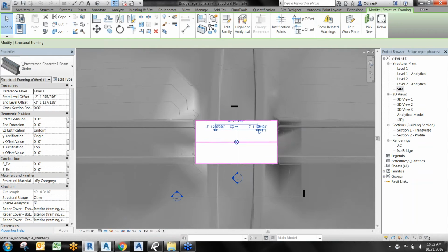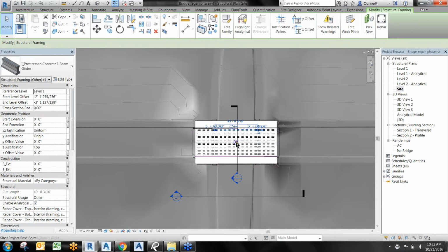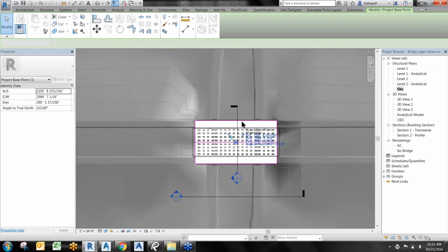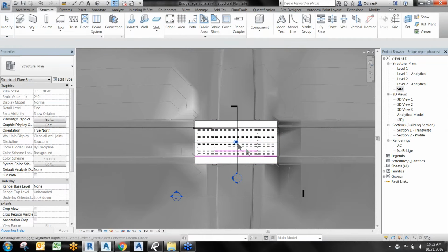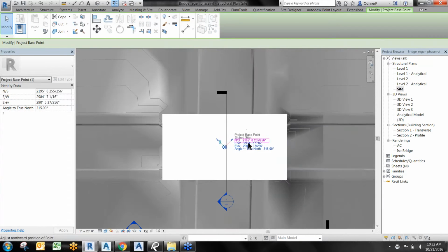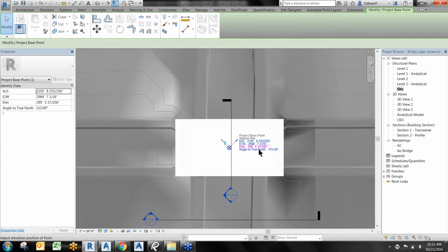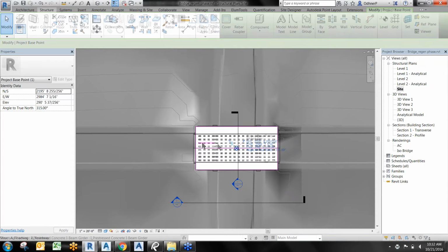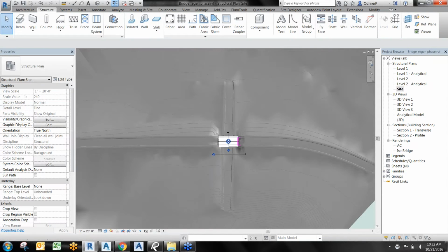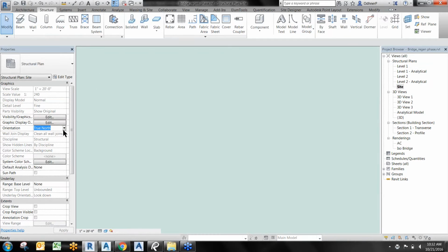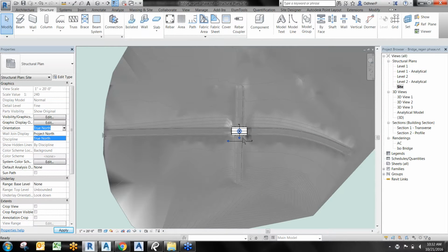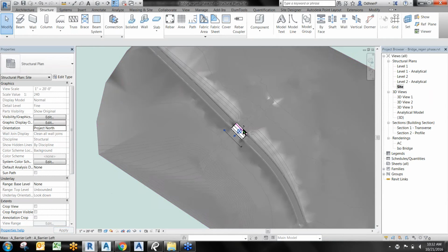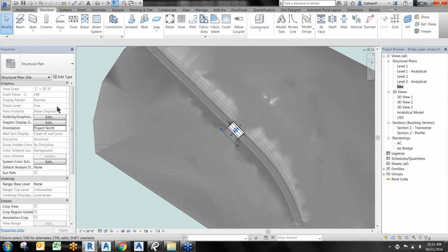And right here I have, remember the opportunity I had, if I click on this component here, you can see we can set Revit to, I actually set it to 315 degrees over an angle to true north. So any view that you go into, you have this opportunity of going over here. Once you set that shared coordinate, you can go back into Project North and go back to the original orientation. So right here, to place our components, we're going to go back to True North.